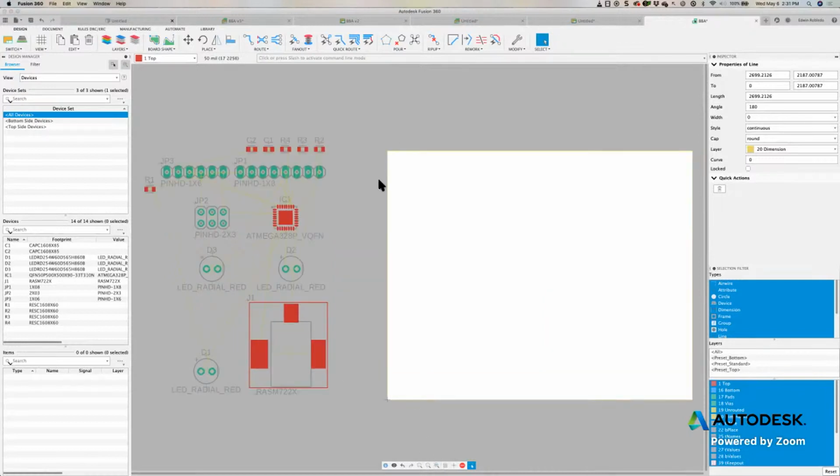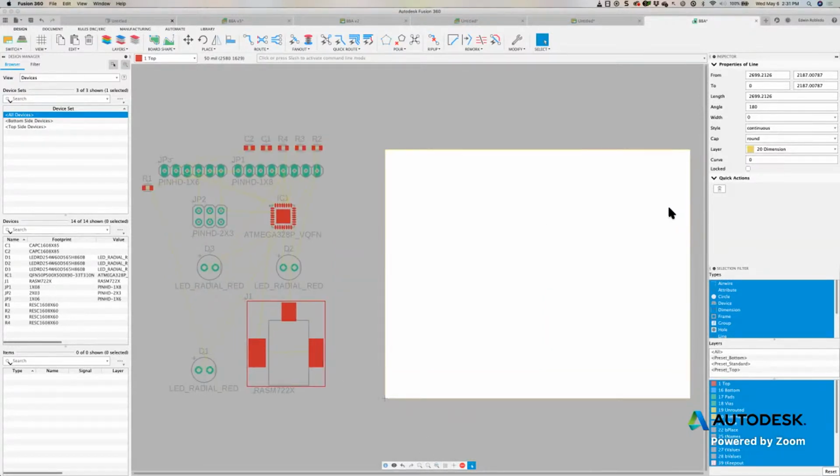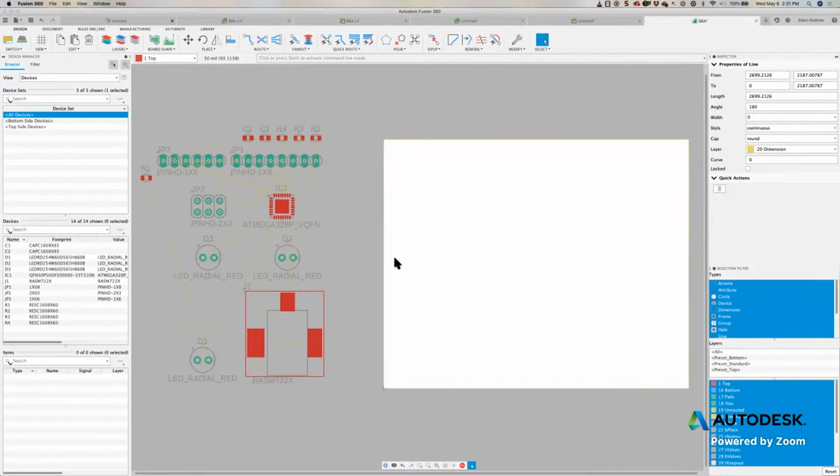Okay. So as you could see, I left clicked and dragged the board outline that came through. I'm not going to be really careful with my placement because I just want to optimize the amount of information that I get. I'm just going to start moving my components. As you can see, the components come up with a little crosshair. That's the origin of the component, just as it is in the schematic. Notice that the background color of my board is different from the rest of the drawing area, and this is intentional.